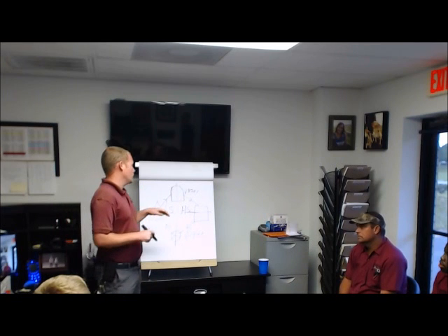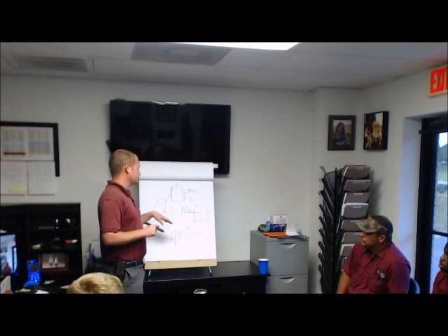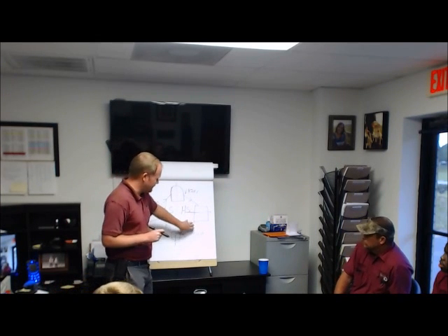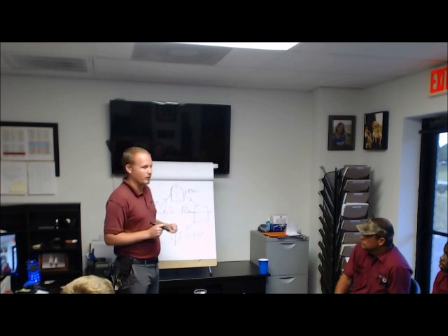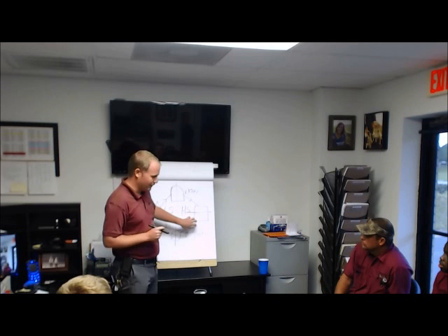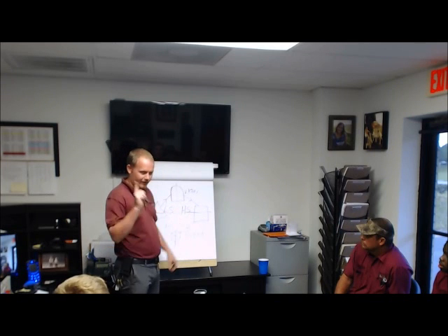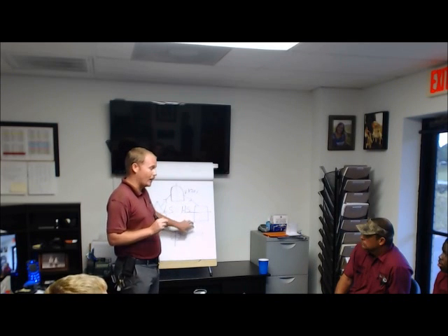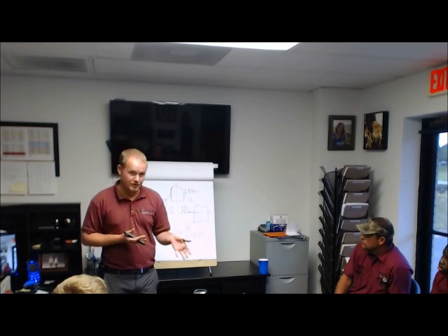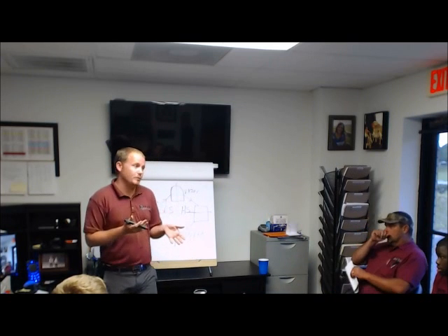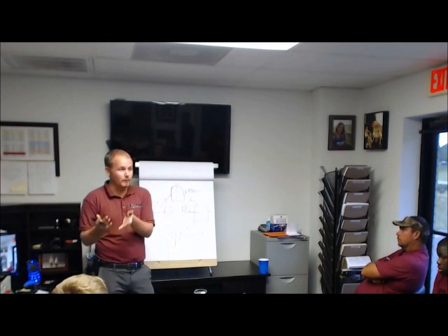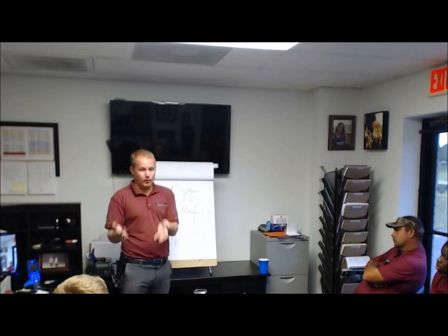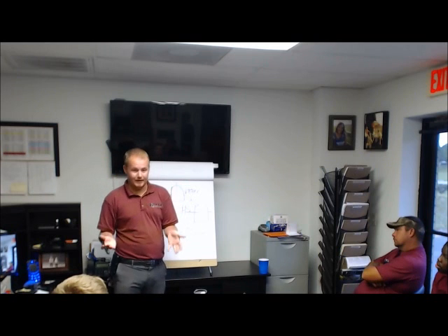So what we want to know here, as it pertains to the liquid line, is that when we're taking readings on the liquid line, we want to make sure that we've got liquid in our liquid line. That's step one. Second step is to try to take the readings based on what the manufacturers suggest in order to tell us, do we have a correct subcool? Okay? And this is like what I was saying, it's super important that you make sure that your equipment is as well calibrated as it possibly can be.